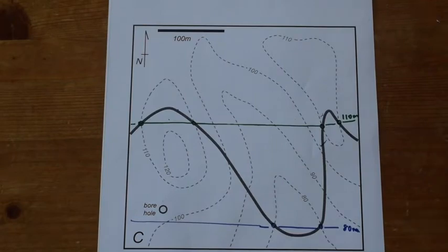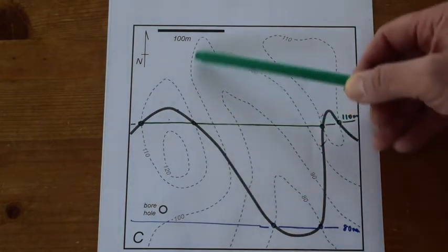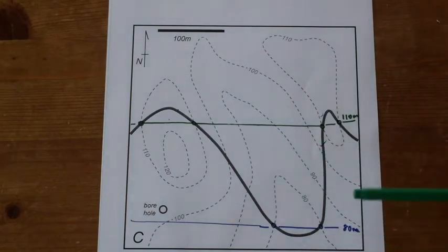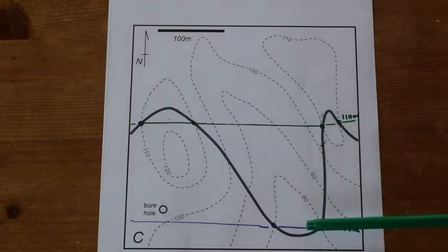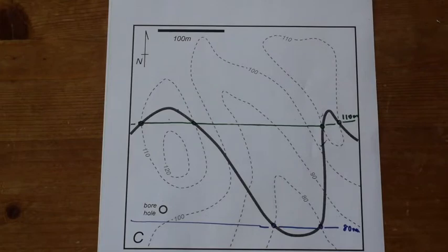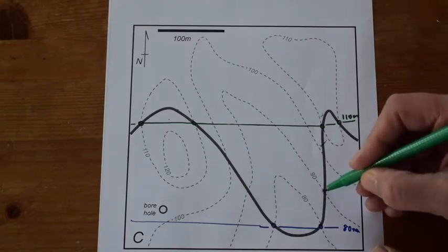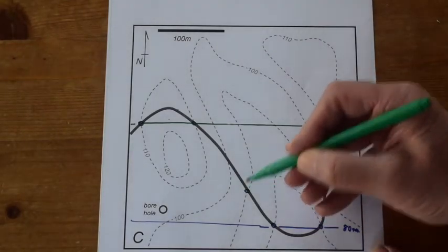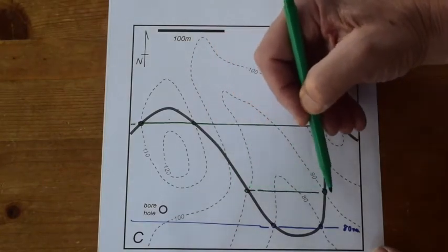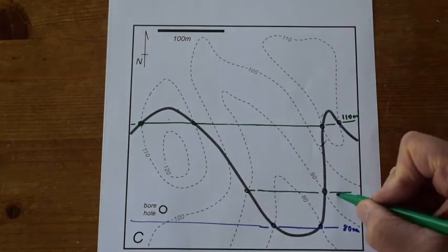Okay, so there are more structure contours we can draw because we have the intercept of the 90 metre topographic contour and the 100 metre topographic contour with the boundary, which allow us to draw 2 more structure contours. If this surface is perfectly planar, these contour intervals should be equally spaced on the map. So let's see how we do with that. Here's the 90, and just draw that in. I'll just draw it across this area first to make sure that it's working okay. So that's the 90 metre.